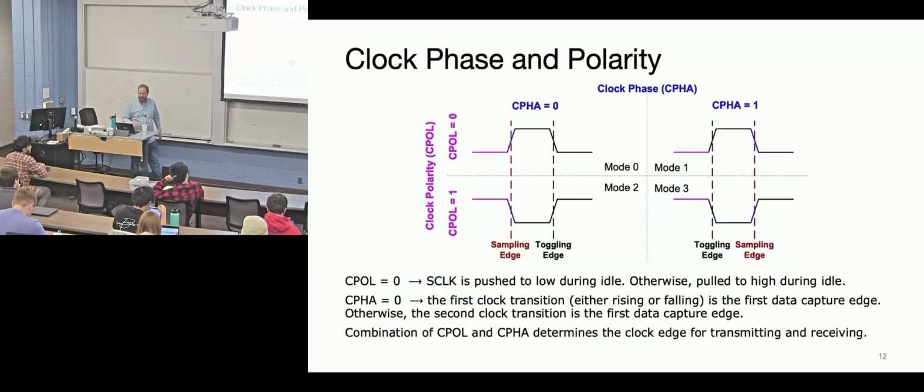All right, so first let's try to understand whatever this is. This is saying the clock could be in 4 different modes. And one of the modes is that the clock starts high. It's normal. Resting state is high. And so that would be these 2 bottom ones. And then these 2 are when you clock in data. So you're either clocking in high, or the rising edge, or the falling edge.